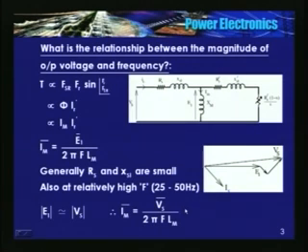We also discussed one of the possible cases in which we kept Vs constant and tried to reduce frequency. Since we are decreasing the frequency, synchronous speed will fall. Vs is held constant, f reduces, therefore the magnetizing current increases. Therefore, the equation says that if the magnetizing current increases, flux also increases.